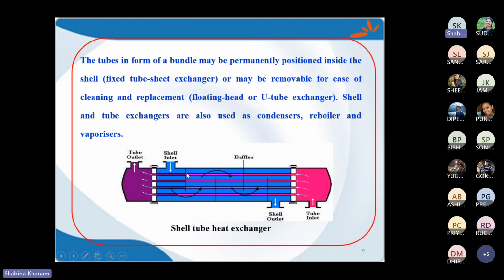Another thing is, if I need to place another baffle, again I need to put a spacer from this distance to this distance, and that spacer will decide the location of this. Similarly, from this baffle to this baffle, again we need to insert a spacer. So spacers are used to have uniform distance between two baffles. So in that way you can have regular placement of baffles in the heat exchanger. These are some of the points.